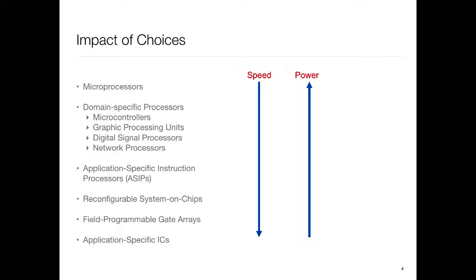And the reason is the following. Let's say I want to do 1-bit AND. Well, that would be just an AND gate here, but it would be a whole 32 or 64-bit instruction up there. So there's a lot of wastage going on. The other thing is up here, since it's designed for a general purpose workload, there is a lot of hardware which maybe your application will never exercise. They're still sitting there, and if you need bit widths which are different, then again a lot of inefficiencies out there. So generally more wastage and more unused stuff, whereas here you are able to optimize it.